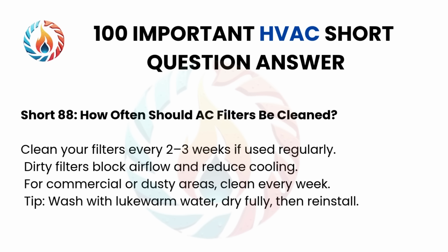Short 88. How often should AC filters be cleaned? Clean your filters every 2 to 3 weeks if used regularly. Dirty filters block airflow and reduce cooling. For commercial or dusty areas, clean every week.